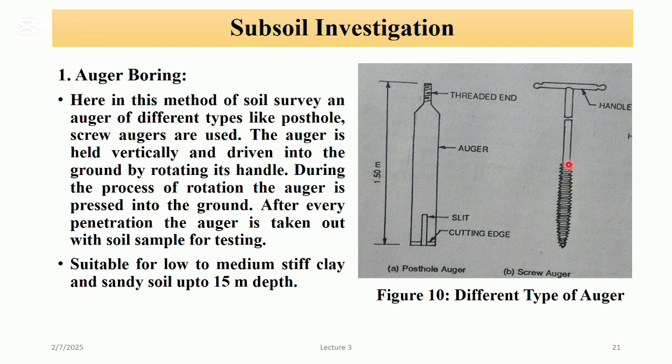This type of boring method is best suited for ordinary buildings to be erected in clay or sandy soil. It can be conveniently used for soil penetration up to 15-meter depth. But this method is not adapted for deeper holes or ground where gravel, boulders, or compact material is present.